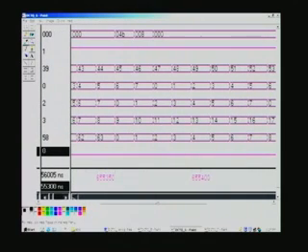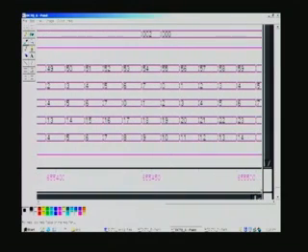This is towards the end of all the 1024 blocks being processed. So, that is the start here. This 4B is now shown not in decimal but in hexadecimal, just for a change, because the output file arrives only in hexadecimal, and you can see that the first AC coefficient here is 8, other things are 0. As we mentioned before, DCTQ succeeds in making most of them zeros, only a few non-zero coefficients will be there. First coefficient will always be a very high value, that is for the DC coefficient, sorry, and this is the last but one block that is processed here, and so towards the end it keeps going.